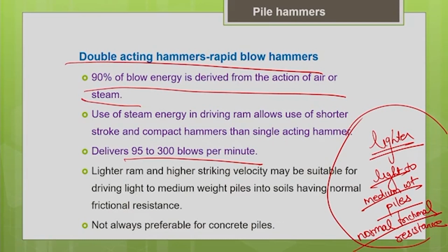So, it is very high when compared to the single acting hammer. Such a high blow rate can easily damage the concrete pile. That is why it is not recommended for the concrete pile. So, let me summarize what we discussed.